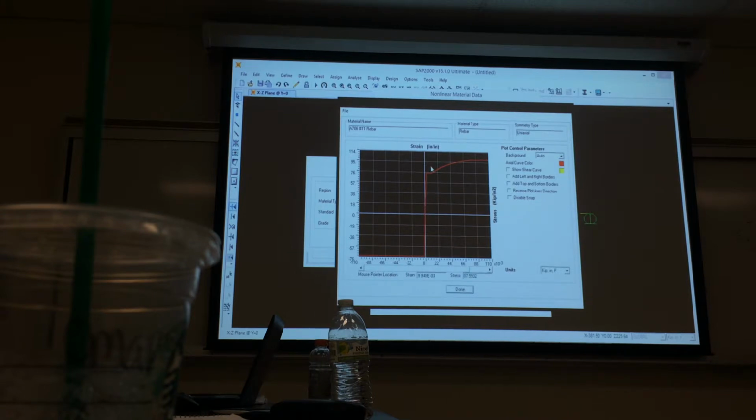Okay. So all I did for this was tell SAP I've got 2 points in my compression region. I've got linear elastic, I yield, and then I'm elastic after that. So elastoplastic response. This is the best way to model, let's say, buckling behavior very, very simplistically. And then for the tensile region, I just used Mander's model for steel, and I picked 8 or 10 points, so that I'm capturing the linear elastic region, I'm capturing the yield plateau correctly, and I'm capturing enough points on the curve. You can see that matches overall pretty well.